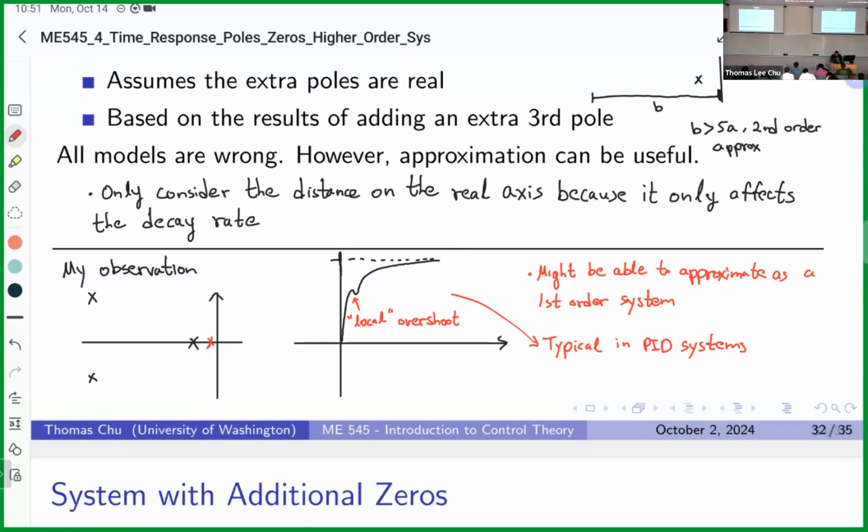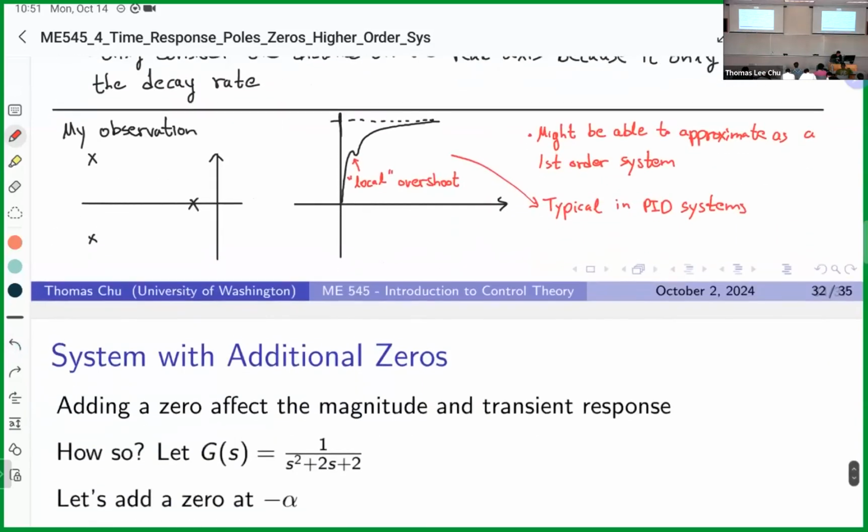So you actually might see it with the PI response because it's specifically the integral part of the controller that adds a pole really close to the origin. But when I say PID, it's because the derivative part of the controller will also increase the system order. So you're guaranteed to have a higher order system with PID controllers. Hope that answers your question.